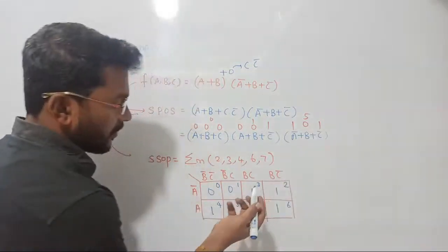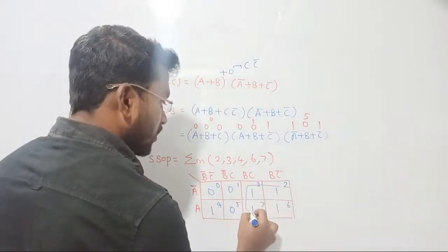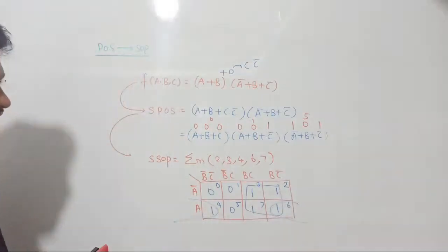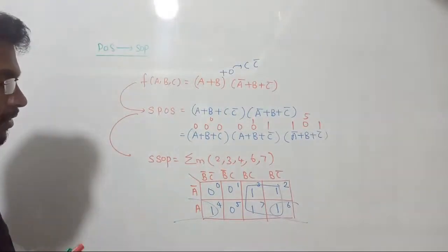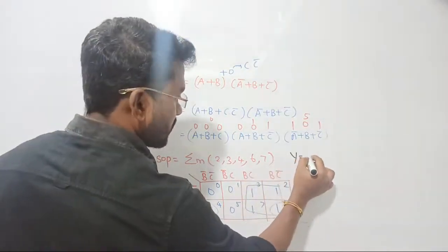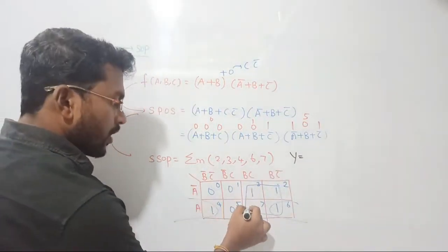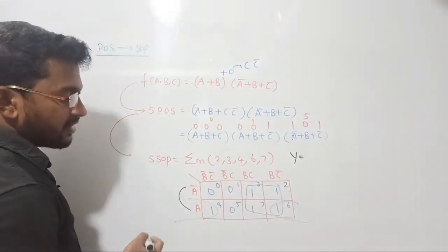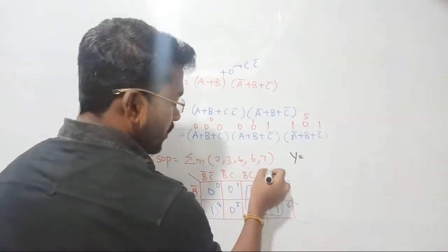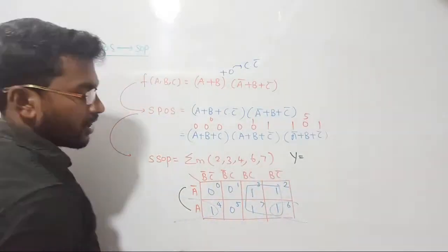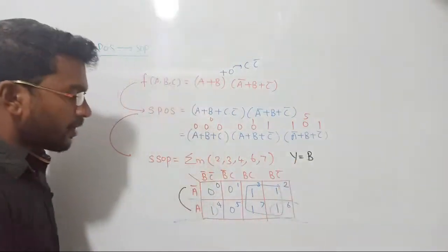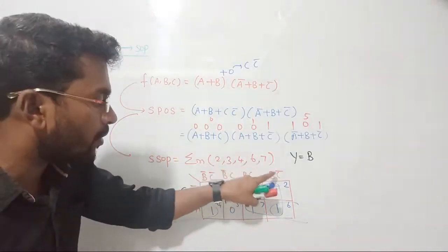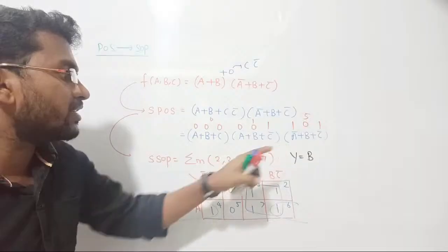Anyway, an 8 grouping is not available, but a 4 grouping is available. See there, we can group all these together. 2 groupings are also available, such that in one step we can write the answer in the K-map. So what is the answer? Y can be written as, if I consider this 4 grouping, we add these two so that a + a bar equals 1. Similarly, the common variable is b, so the correct answer is b. Because b into 1, here we add these two, a + a bar will be 1, so 1 into the common term b is going to be b only, right?